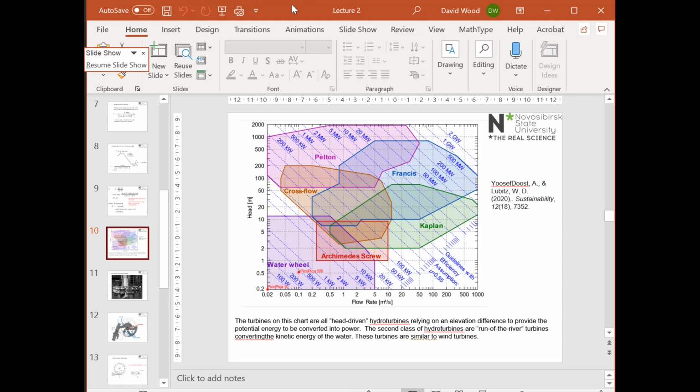My understanding, and this is really stretching my knowledge of the practical applications, is that generally the Francis is preferred partly because you have a higher level of control over its operating conditions. A Francis turbine has inlet guide vanes, so you can do a lot of mechanical control as well as speed control.